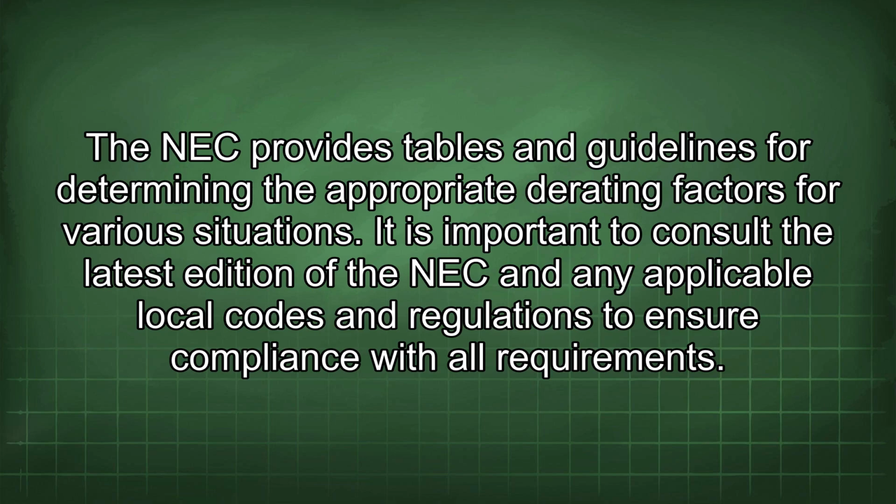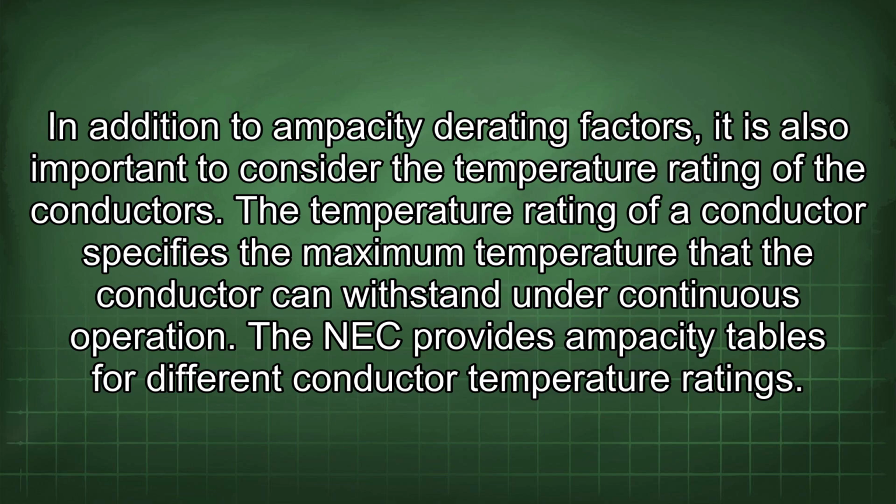In addition to ampacity derating factors, it is also important to consider the temperature rating of the conductors. The temperature rating of a conductor specifies the maximum temperature that the conductor can withstand under continuous operation. The NEC provides ampacity tables for different conductor temperature ratings.